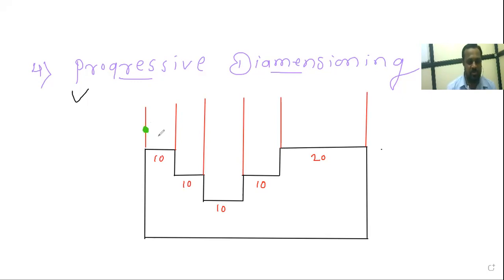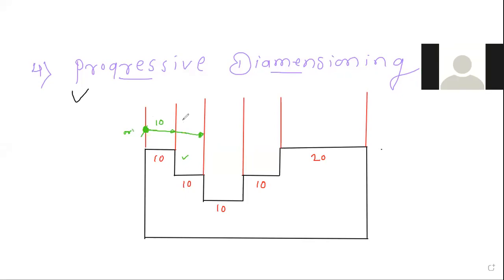Now see here how we have to show it. Simple. Suppose we have to show the dimension of this part. We just draw the dimension line like this, and show the arrows here. And what is the dimension? Yes, 10 centimeters. Then suppose we have to show the dimension of this part. Again, from this arrow, we draw one line, and only on one side we draw the arrow. Don't show the arrow on this side also. And suppose we have to show the dimension of this second part. We have to count the dimension from this origin only. Then tell me, what is this dimension? 20 centimeters.